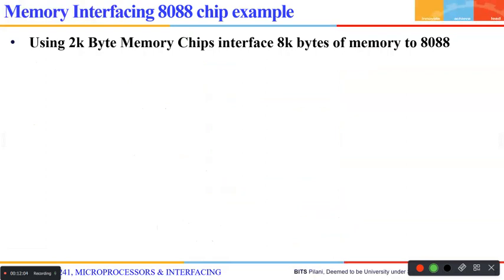You don't need the extra. 16-bit means you need more silicon, more transistors, more flip-flops. 16-bit means 16 flip-flops are required. If I say only 8-bit, you need only 8-bit. Your ALU, your registers, everything is 8-bit only. You're going to have savings. So the cost of the 8088 chip is less than the cost of the 8086 chip.